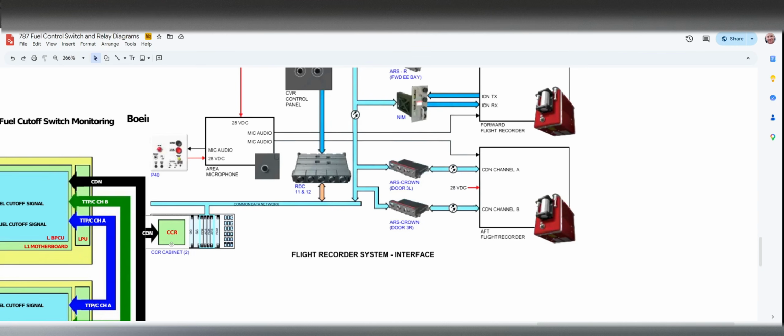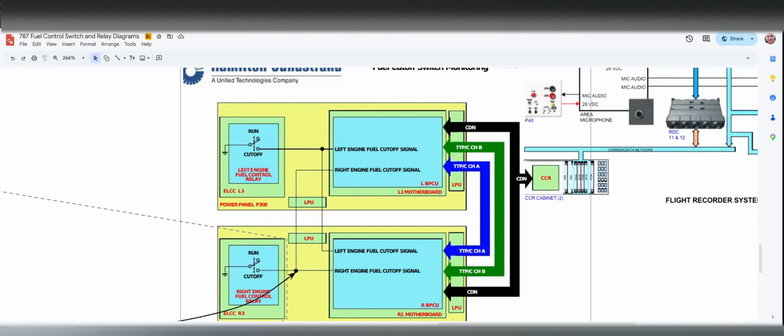The signal that you have been told was someone transitioning the switch from run to cutoff was not. This relay is a dual coil electromagnetic latching relay. A dual coil electromagnetic latching relay must be wired in polarity correct. The coils work against each other, not at the same time.